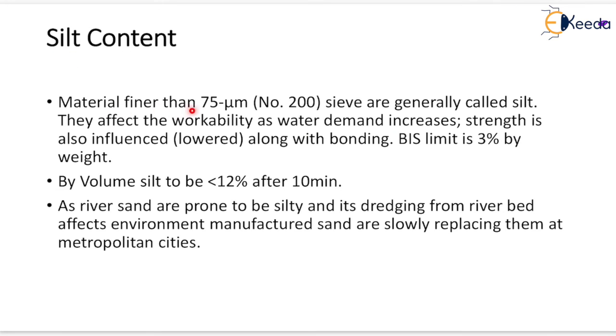Material finer than 75 micrometer sieve is generally called silt. It affects the workability as water demand increases. Strength is also influenced along with bonding. Bureau of Indian Standard limit is 3% by weight. Now, by volume, silt is to be less than 12% after 10 minutes.